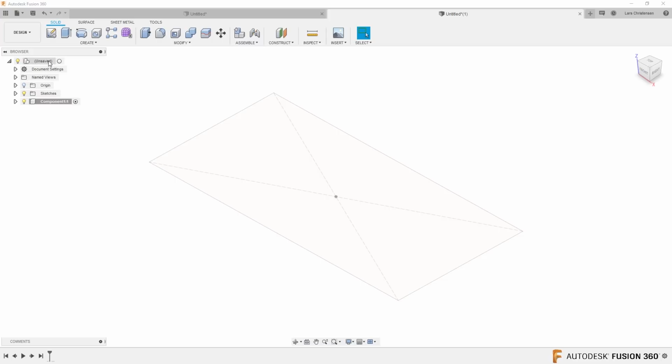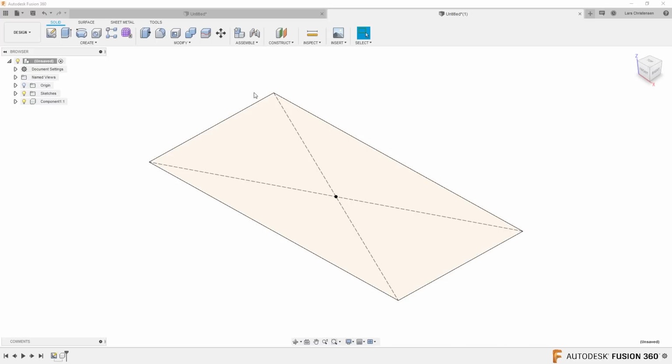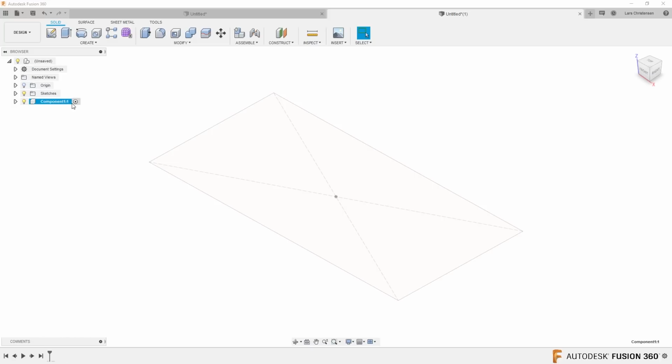Now if I go back up to the top and I activate that fisheye component, then my sketch comes back up. And you will now see that anything that happens from this point downwards is now assembled down the timeline. So I have the first sketch we created, and I have that new component we just created. Now again, if I switch back to the fisheye, notice that the component has nothing in it yet.